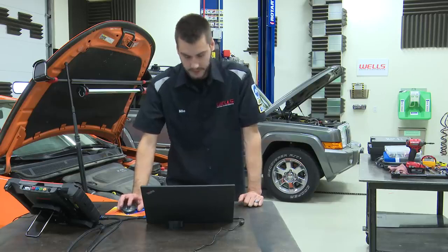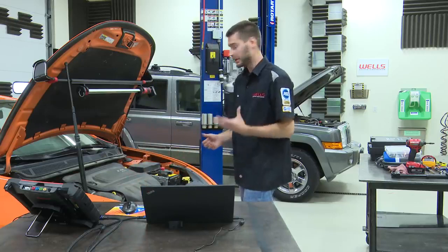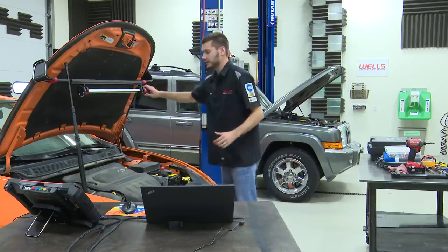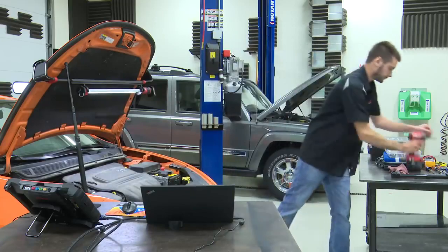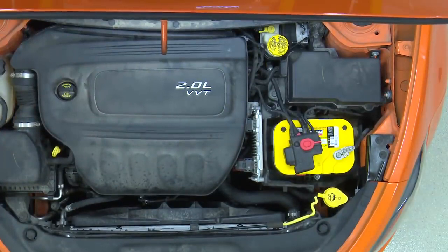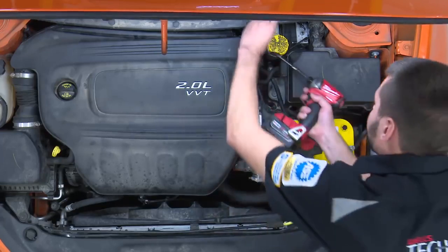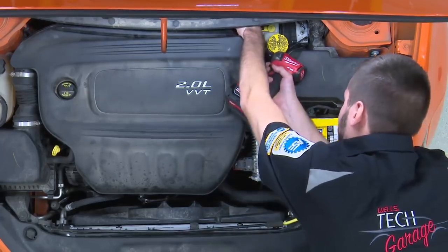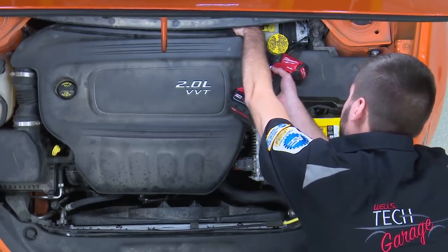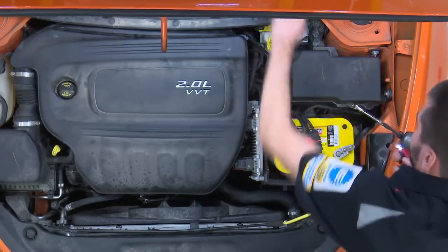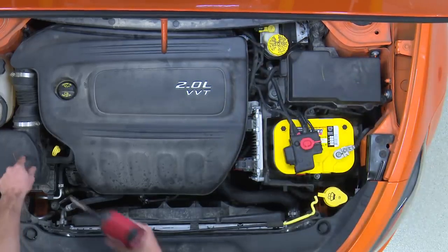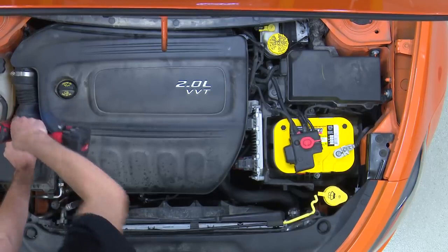All right. But because it's telling us to do that, why don't we go ahead and do that? So I'm going to first of all get some stuff out of the way here. Of course, that's not going to be the same size. I really like how these air boxes, or this whole plastic shield assembly here, come off. We've got a clamp back here on the throttle body that happens to use a 7mm clamp, or maybe 1/4 inch, whatever it might be. And over here on the actual airbox side, we're looking at an 8mm. Couldn't just stay consistent.